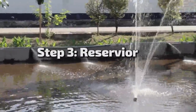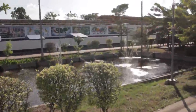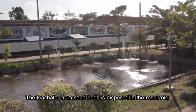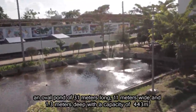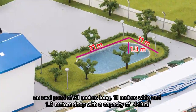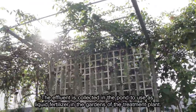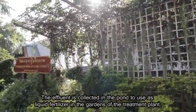Step 3. Reservoir. The leachate from sand beds is disposed in the reservoir. An oval pond of 31 meters long, 11 meters wide, and 1.3 meters deep with a capacity of 443 cubic meters. The effluent is collected in the pond to use as liquid fertilizer in the gardens of the treatment plant.